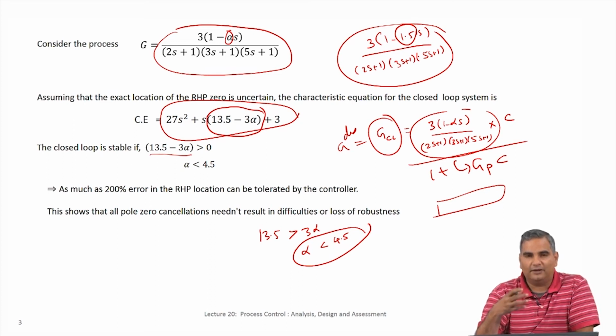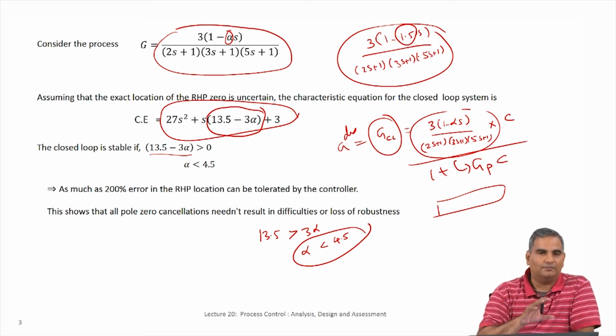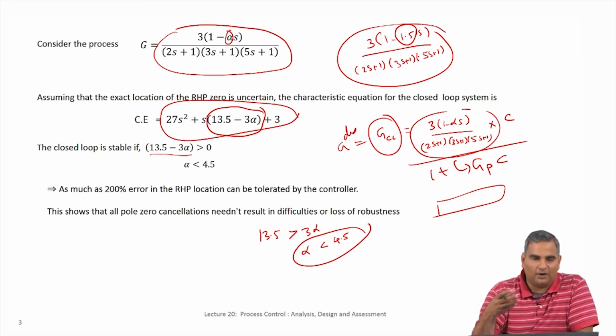I mean, when I say it, I am talking about the model not being used online. But in the next thing which we are going to talk about, which is how do you control time delay systems, you will see that the use of the model will be more explicit even in the controller calculation. So, you cannot simply live with the PID, but on top of a PID you will see that there are some model related terms that come in the controller computations online. So, without the model you cannot implement the controller. In the other case, once the controller is designed, you can directly implement it.